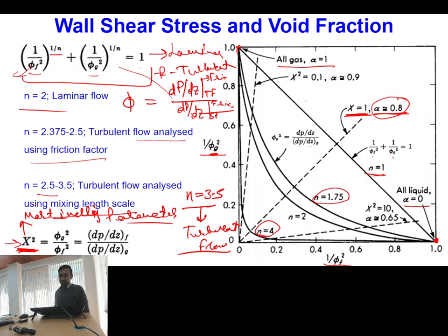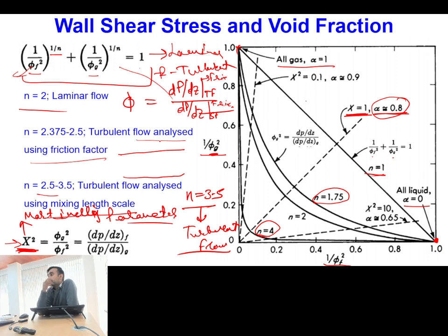So people have taken a constant sized pipeline, and in that pipeline they have considered purely adiabatic conditions, meaning they try to maintain the same value of volume fraction so that there is not much acceleration of the fluid within the tube section in which experiments are performed. And the third thing is pipes were purely horizontal, so the gravitational component was not involved.